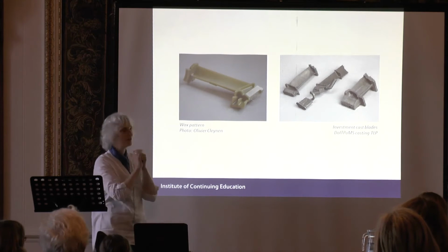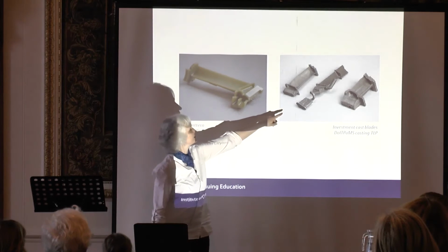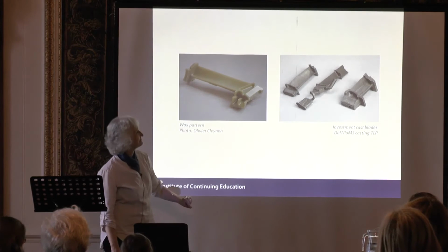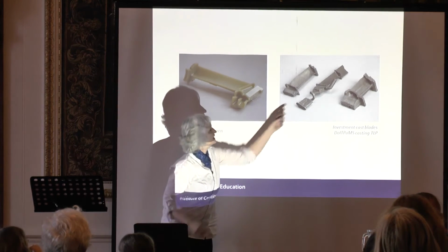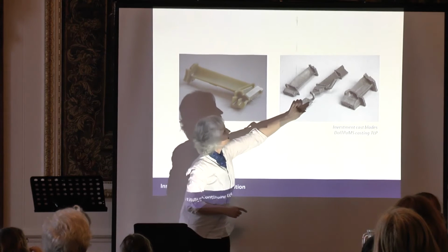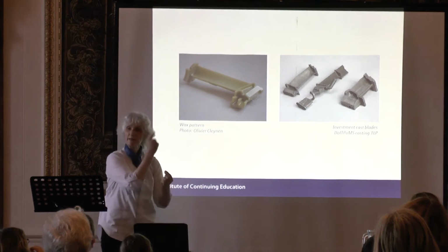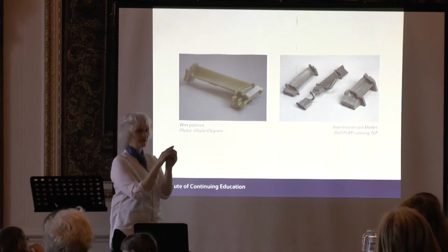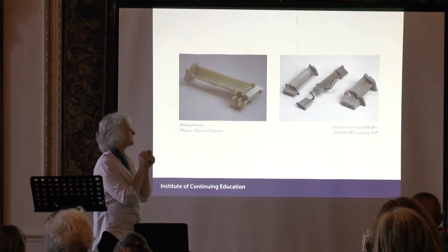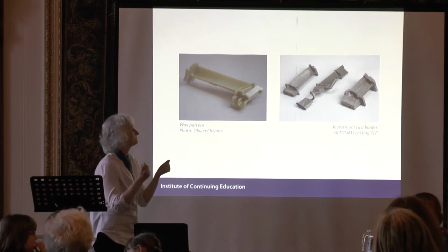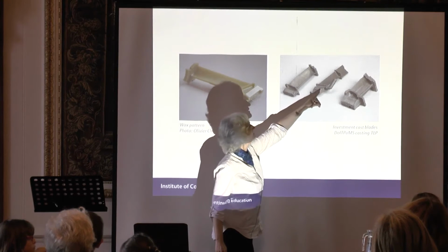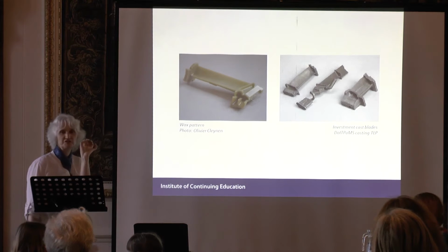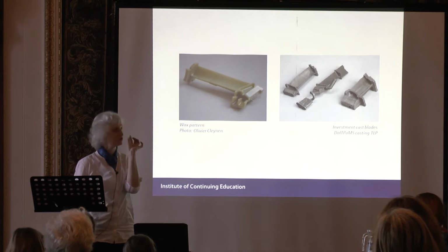And the way we get rid of all those boundaries is we start off with a little seed, like this little object here on the left, and then it's allowed to solidify slowly up this helical piece, which is called a pigtail. As it goes up the pigtail, whichever of those arrangements of the atoms is the most favourable wins over all the others. So by the time you get into here and into the blade, instead of little grains a fraction of the size of a grain of sand, we have just one grain.